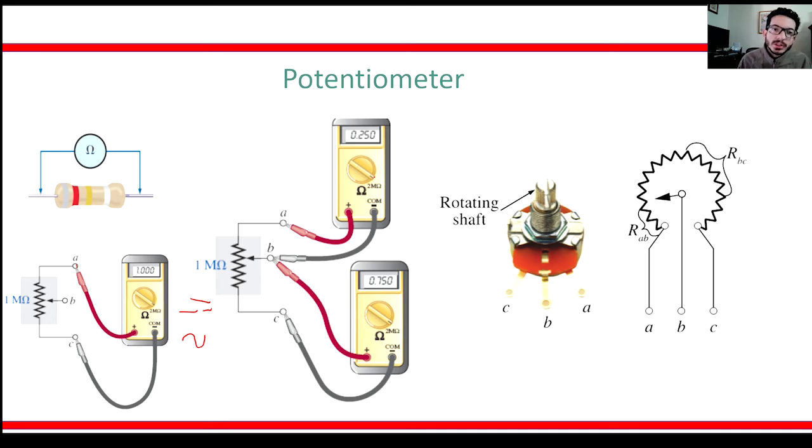But you can also measure the resistance. There's an ohm resistance setting on the multimeter, and what you can do is just measure both ends of the resistor. It will send a fixed current and voltage, and it will measure the resistance of the value. It will expect a value back, and it will basically say, oh okay, this is 10 times larger or whatever, so this is the resistance. Basically, you measure the ends of the resistor with a multimeter on the ohm setting, the resistance setting, and you can measure the value of the resistor.